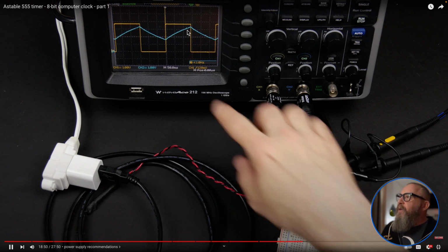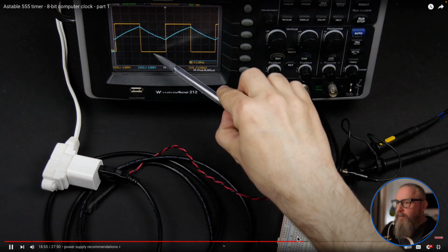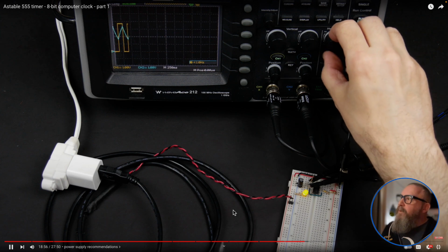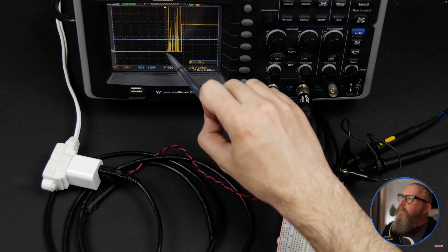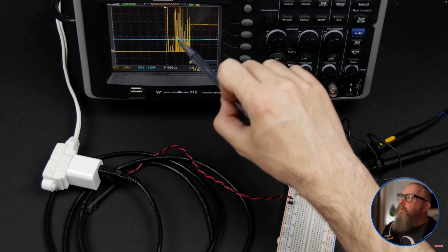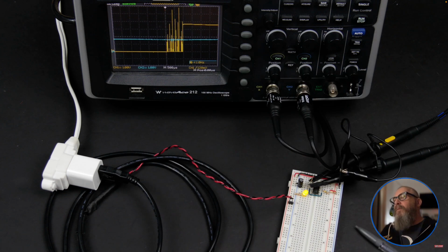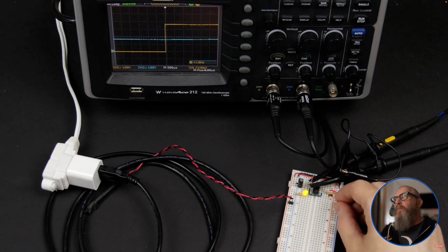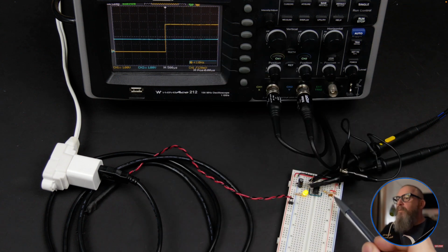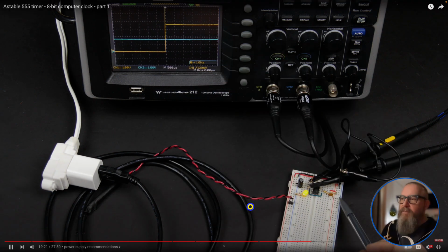It's showing the signal here on the oscilloscope. We see on the scope this nice transition from 0 volts to 5 volts. But if we zoom in on that, what you see is that nice transition from 0 volts to 5 volts is maybe not so nice. There's a lot of junk in there. So if we add this capacitor that they're recommending from ground to pin 5, boom, it clears right up. So definitely recommend that: a 0.01 microfarad capacitor going from pin 5 to ground.